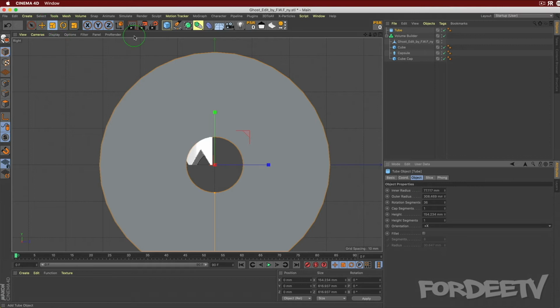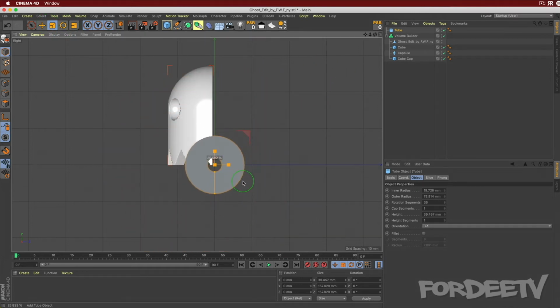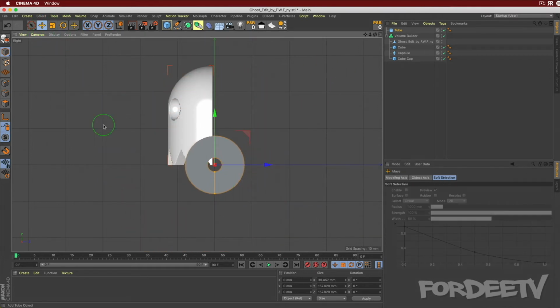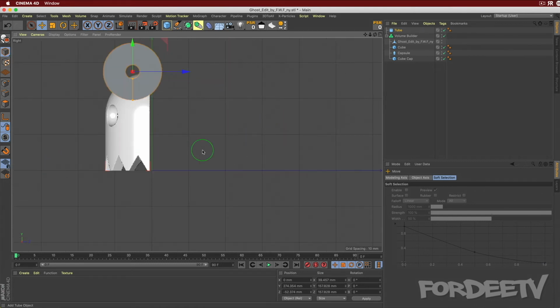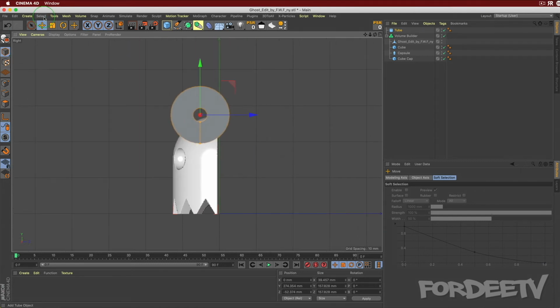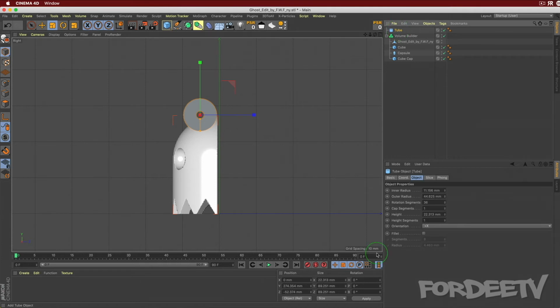Next, we want to stay in scale and we want to drag this down, and we are eyeing this. I'm not doing this necessarily exactly to some scale, I'm just eyeing it. So again, something like this, I'm going to press H on our keyboard, press 1, click, boom. And now we still want to make this quite a bit smaller. Right now I'm not worried about that inner diameter circle. I think when I originally did this, I set this to be 30 millimeters, something to this effect.